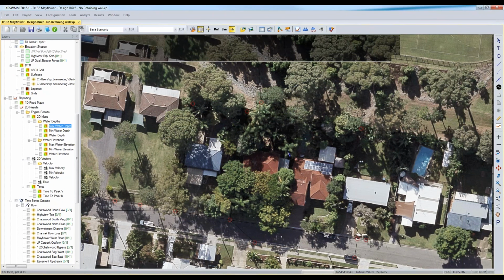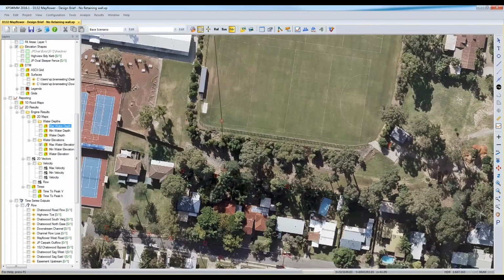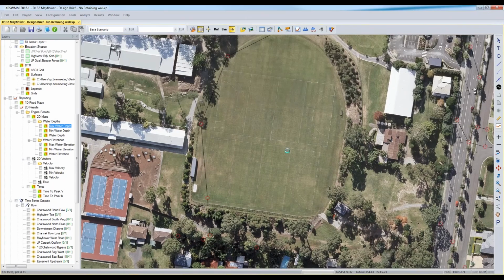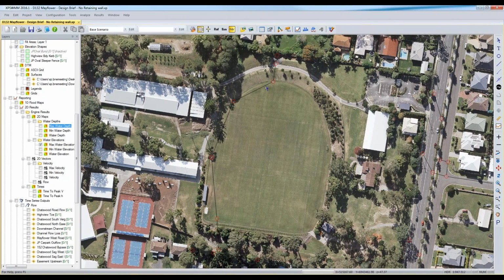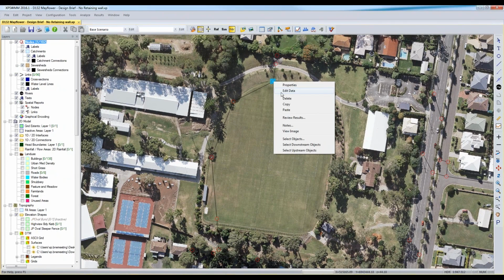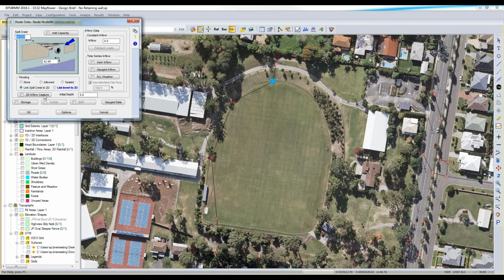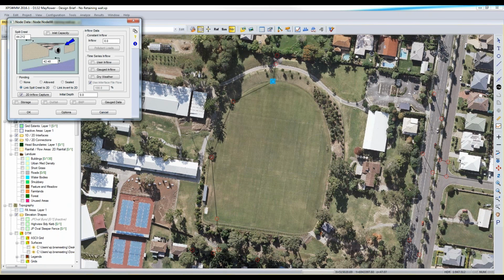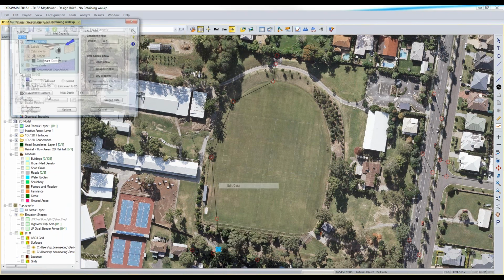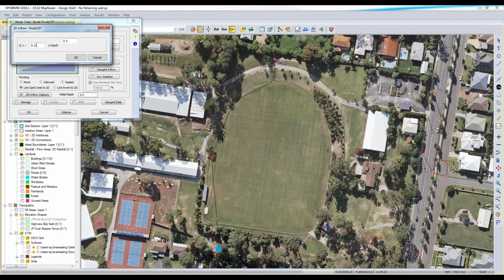So this is Mayflower. This is the one we just looked at. This is the detention basin. That's modelled in 1D, 2D? The detention basin is modelled in 2D. Yep. We've just got the existing pipe network through with the nodes modelled in with the inflow capture, but we've actually worked out the coefficient and exponent based on the grate size, blockage factor, and the orifice. Each one of those is a little tiny field inlet. The big one down here, you expect a bigger coefficient, and there you go. And it was accurate; we've hand calculated it and checked those flows, spot on.